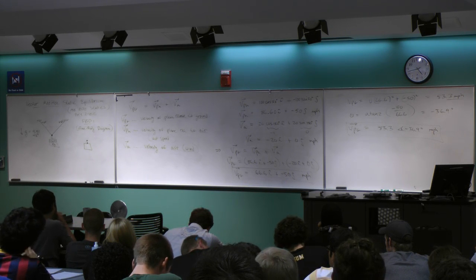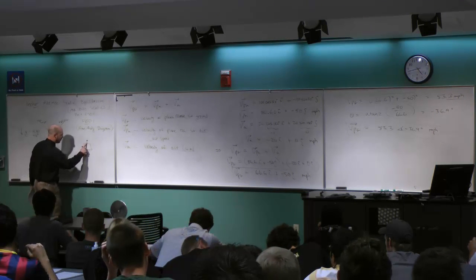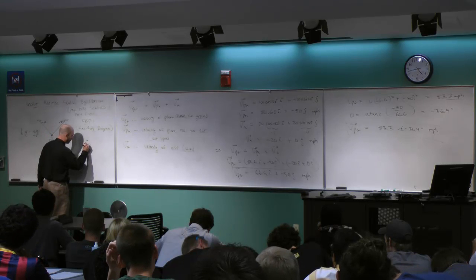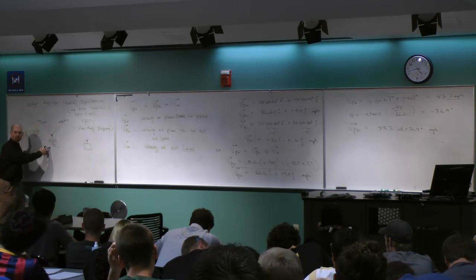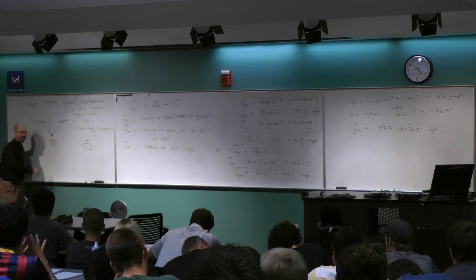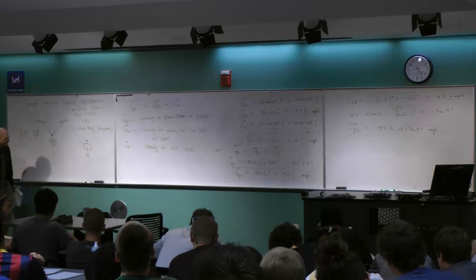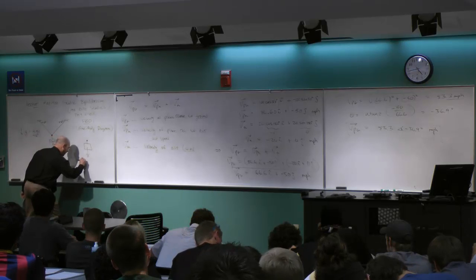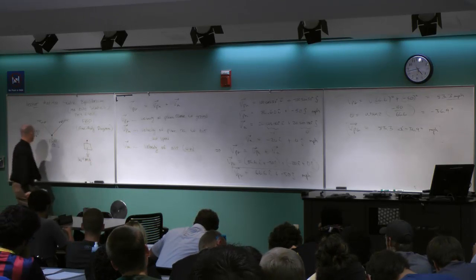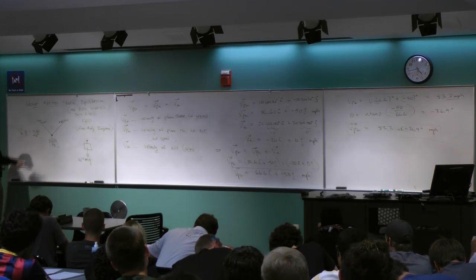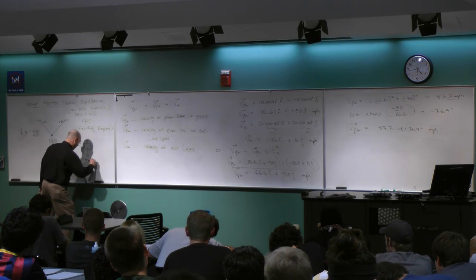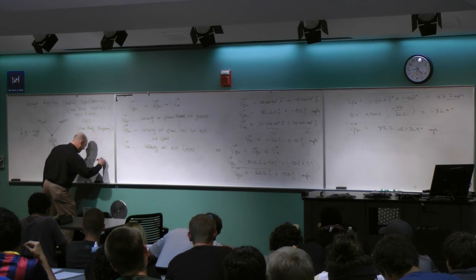Okay, so external forces acting on this entire system here, the question is what's acting? I got the weight of the block, right? So that's mass times gravity is the way I get that. I'm going to call that weight is mg. M is the 1,000. G is 9.81. So this is 9810.